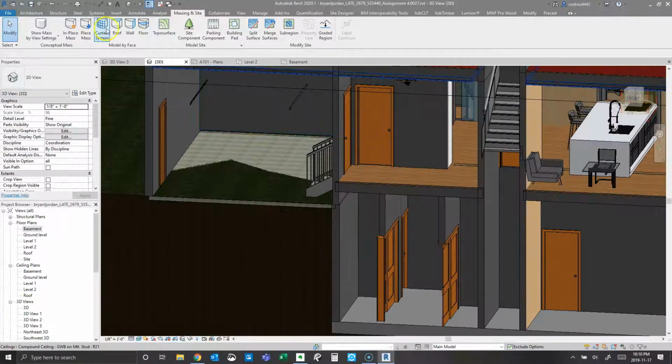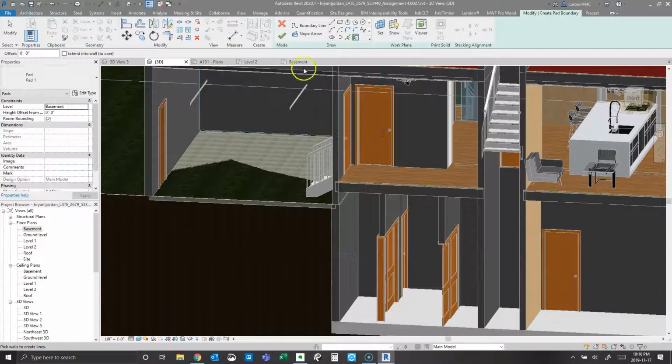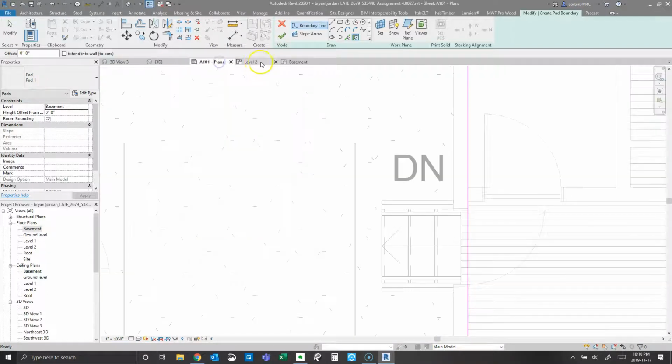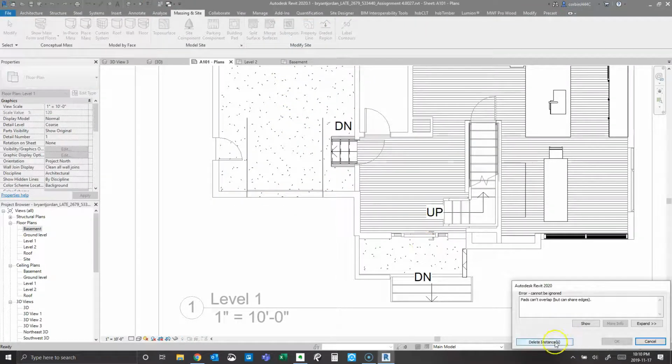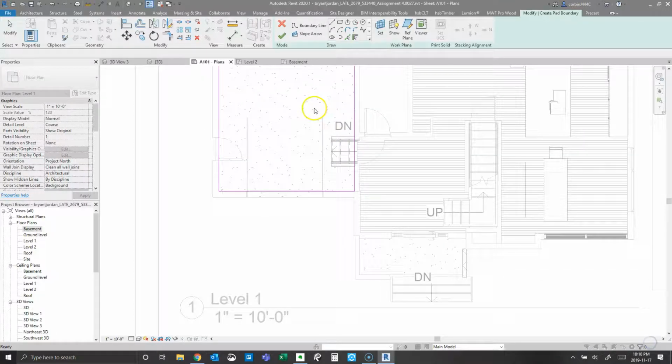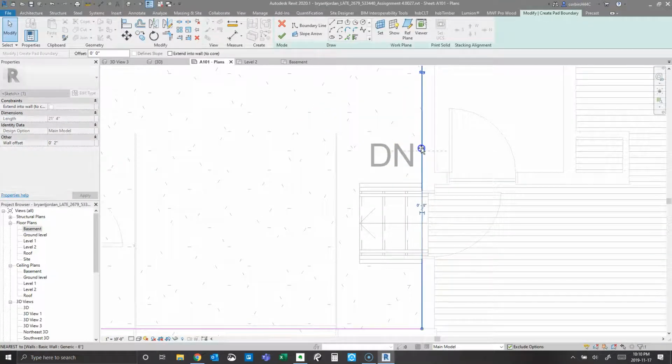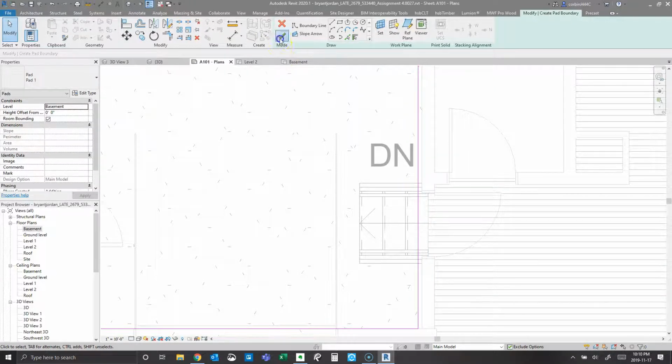We're going to want to add a building pad underneath this garage floor, so I'm just going to pick wall. So because we have a pad underneath, I'm just going to bring this off by 2 inches or something so they don't touch.